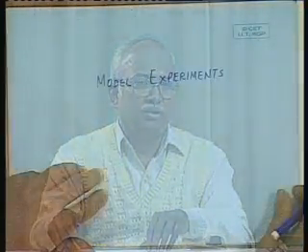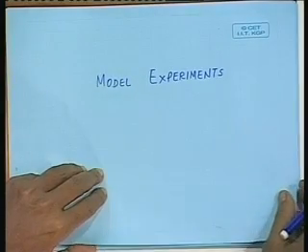Today we will talk about model experiments and extrapolation to full scale. Of course, our model experiments will be limited to resistance test only, and sometimes this experiment is called towing experiment, because as we have defined resistance before, it is the resistance of towing a vessel without its propeller working in water. So, sometimes this is called towing experiments or resistance due to towing a model in a tank.